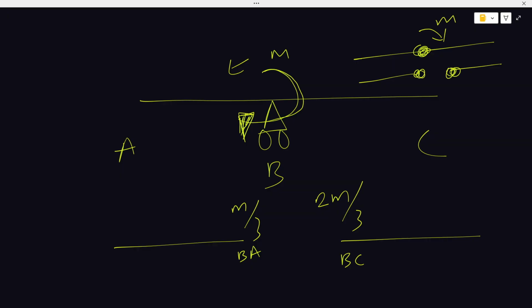Now, the carryover factor that we talked about the other time is saying that, okay, I've distributed to this place, now let me carry over to this other place, based on the second distribution moment. Remember, there are two distribution moments because we have two members connected to that joint. So carryover is saying, let me carry this distribution moment over to this place.